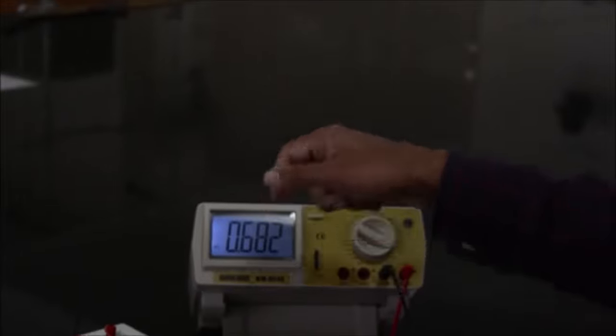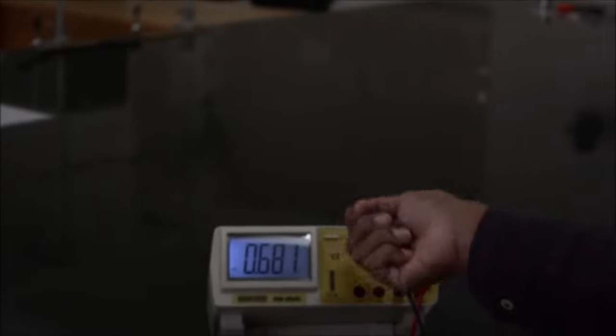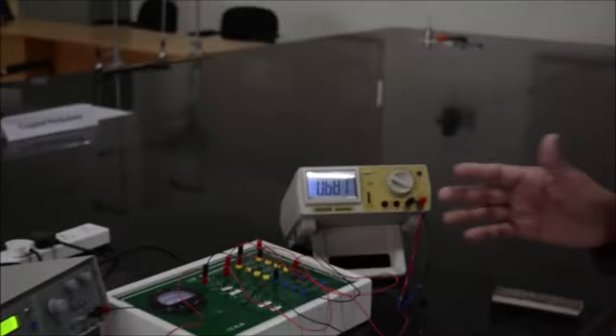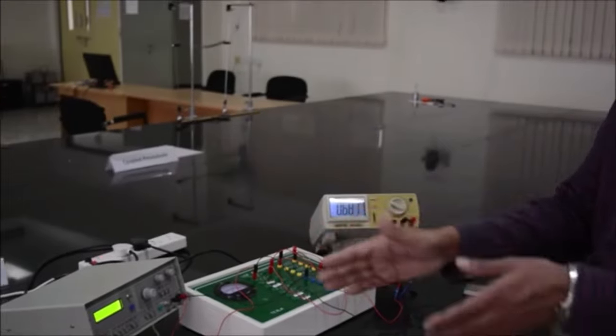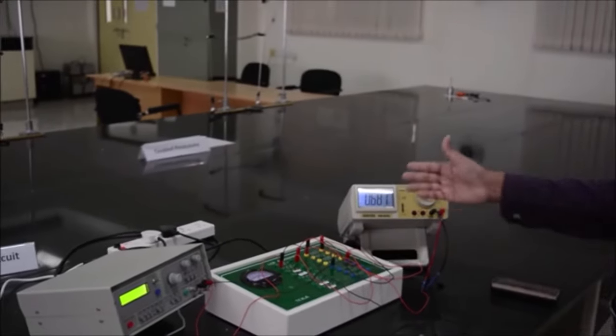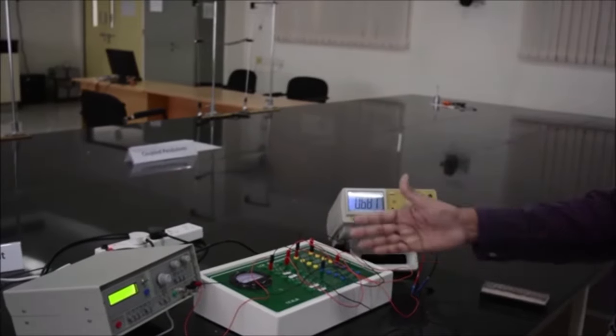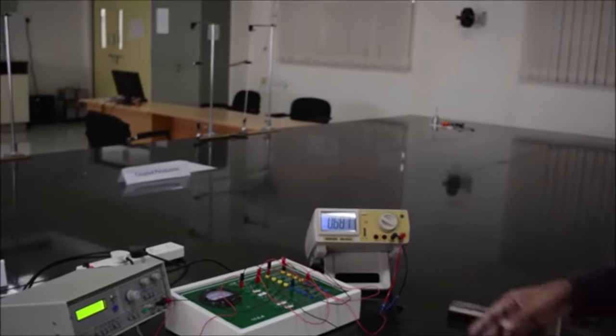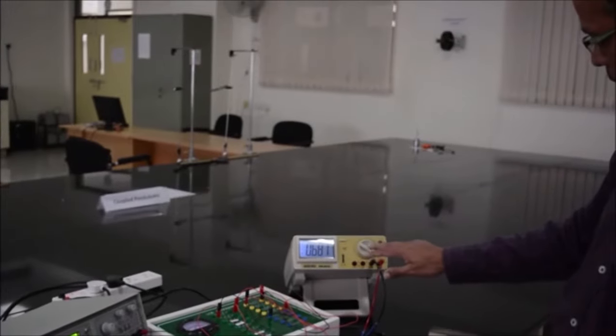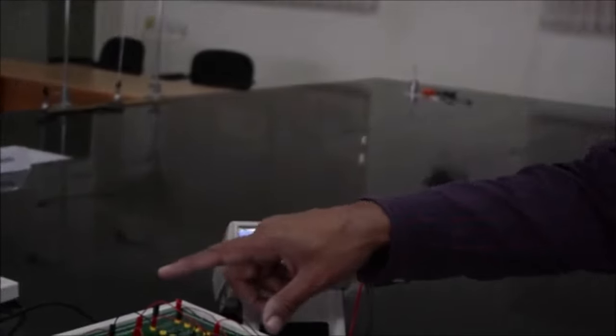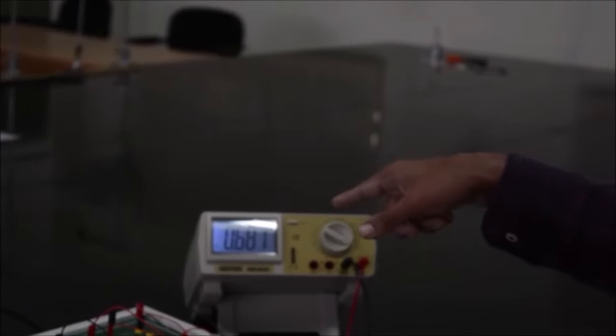Then what would you do? You would change the scale. But that's not a desirable thing. You should never change the scale while measuring voltages. You should have the same scale throughout the experiment. That is why we do the rough sweep, to figure out what is the range of voltage values you will get when you go across the resonant frequency. So please don't change the scale. Ensure that a single scale is enough to capture the entire variation in the voltage values. That is another thing which you should keep in mind.